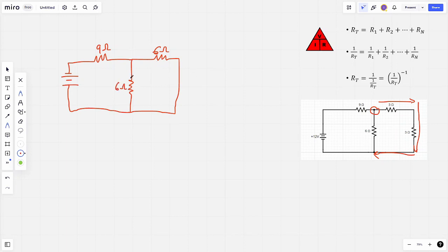So we've established these 2 are in series. Now remember at the start we said this branch and this branch are in parallel, so that means this 6 ohms and this 6 ohms are again in parallel. So remember the laws when dealing with parallel circuits.